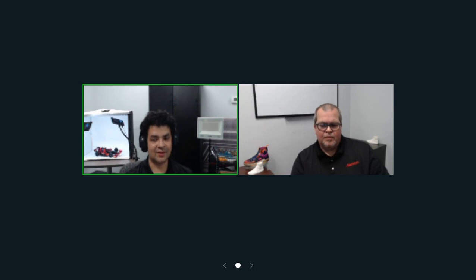Well, that X and Y resolution tends to be overlooked by many people. A lot of people actually focus on the Z-axis resolution. That only defines how smooth your surface is. But the X and Y resolution are very important, especially for people who are looking for accuracy of the machine. I mean, how many details can you get in each print. So this is where the 2207 is going to shine. You cut down a little bit your speed, but at the same time you're getting really nice and crisp detail on each print.